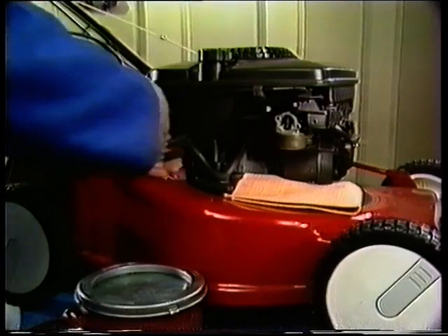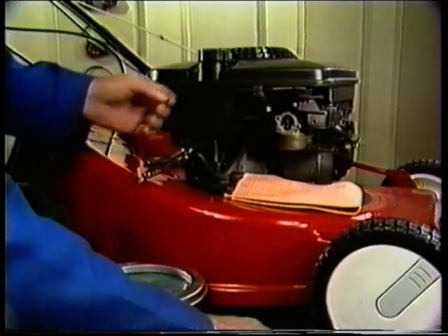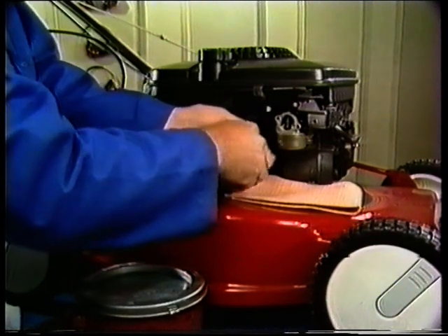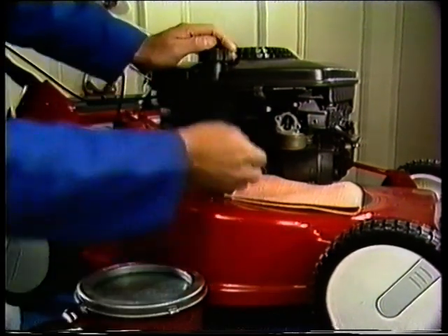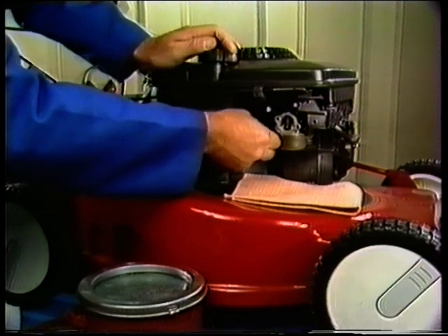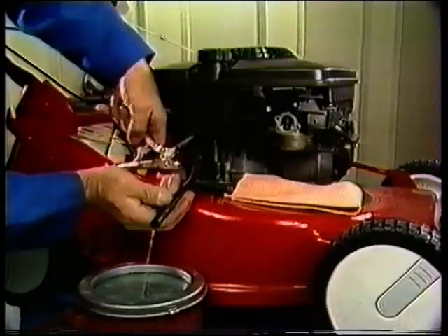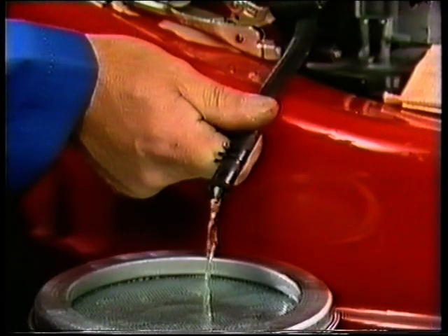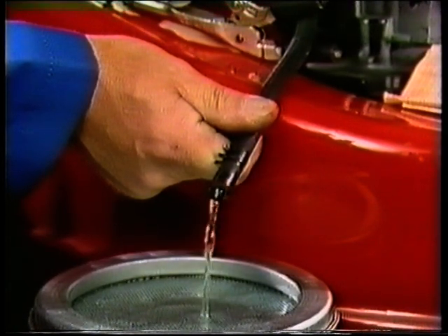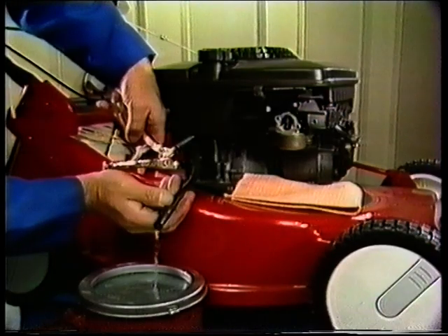The second thing you'll want to do is make sure fuel is reaching the carburetor. Mechanically clamp off the fuel line to stop the fuel flow. Remove the line from the carburetor inlet fitting. Next, with a fuel cap installed, release the clamp and let the fuel run into an approved container. If the flow is as wide as the inside diameter of the line, you'll know that gasoline is being delivered